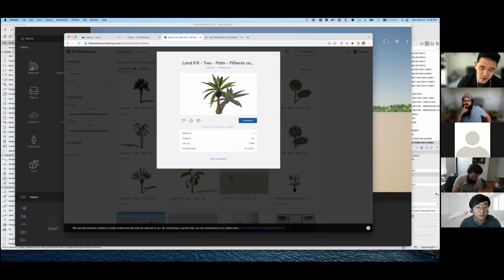If you really need it in Archicad, we can help you put a SketchUp file through Rhino and spit out something that'll go into Archicad, but try and avoid it if possible, and just make your own custom model. If you need furniture, just spend 10 minutes roughing one in out of slabs or maybe morphs to get it close enough.